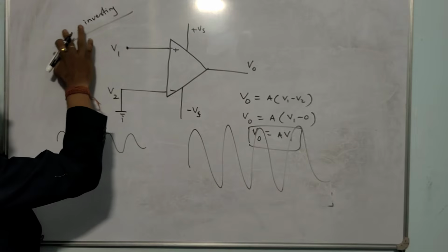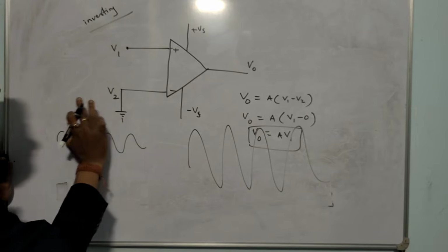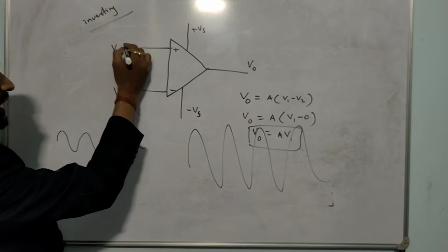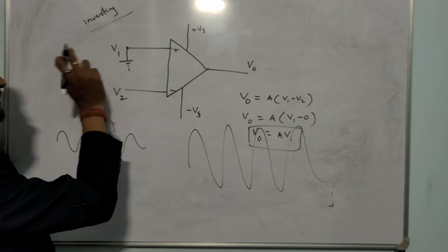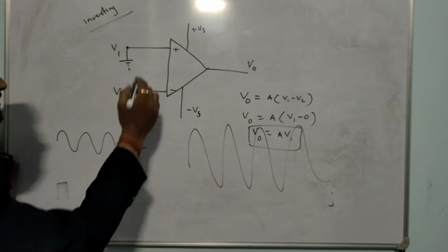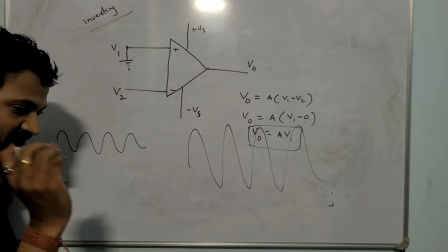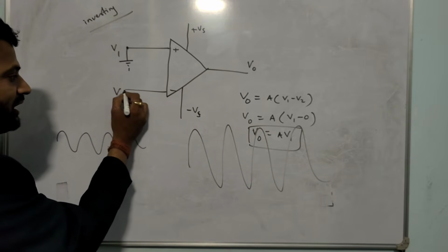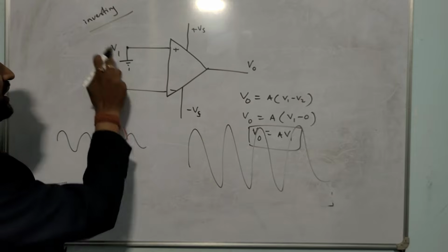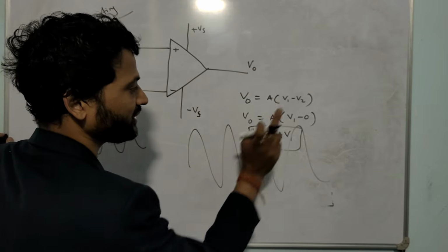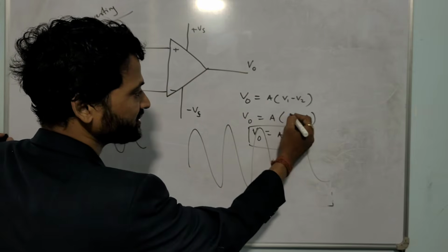अगर इन्वर्टिंग ये हो जाएगा, इन्वर्टिंग होगा मतलब क्या है? You have to activate the inverting mode and deactivate the non-inverting mode. मतलब make it ground. Deactivation activation का concept नहीं है. Just make the V1 ground and activate V2. ये हो गया inverting. अगर ये inverting होगा, what is the output? A into V1 minus V2. So here V2 is 0.